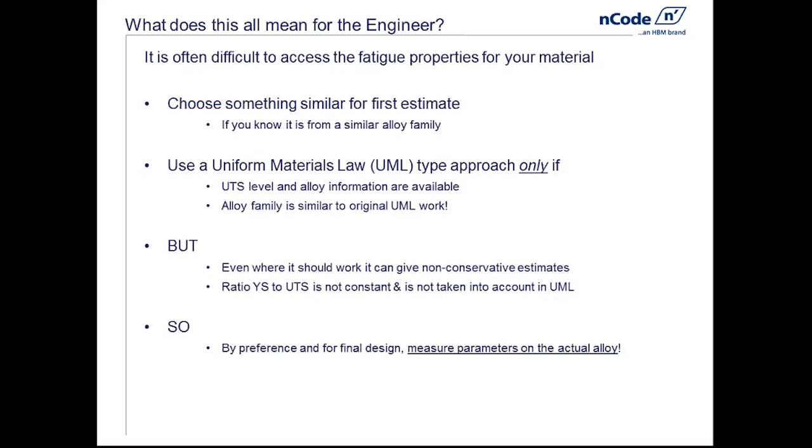Our advice is always, if you're going to use it for a final design, and the weight is crucial and all these sorts of things are critical, then you should measure the parameters on the actual alloy in the condition in which it has been processed. Bear in mind my comment about work hardening, for example. When it comes to casting, if you think in terms of the different casting processes, if you've got a very coarse-grained casting, you'll have very different fatigue properties to something that is finer grained because it's been chill cast or made using a process like squeeze casting.